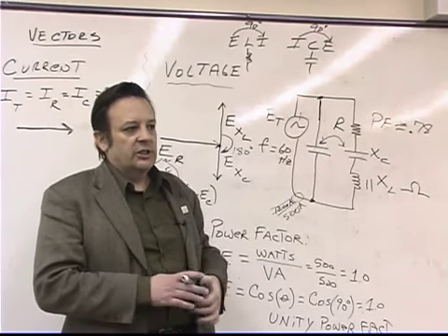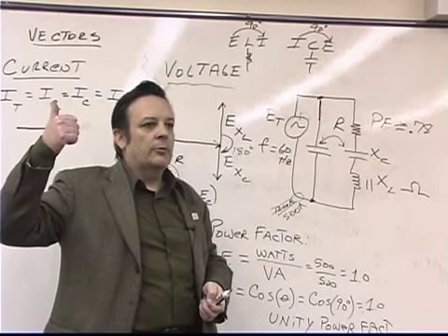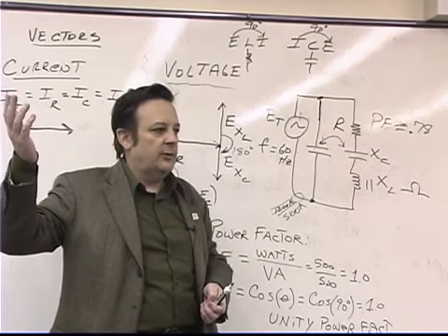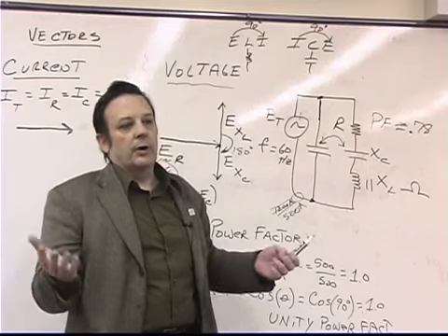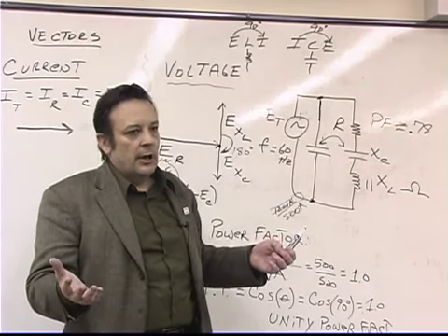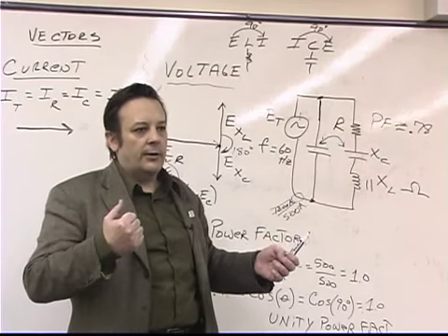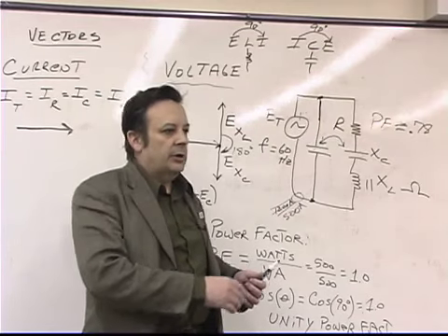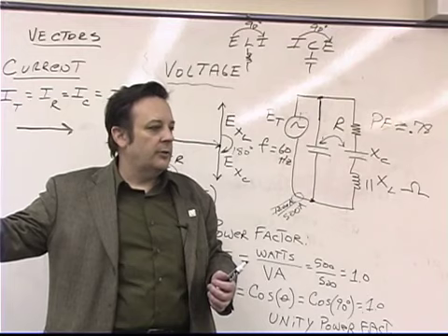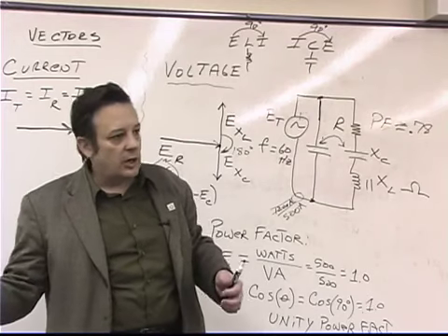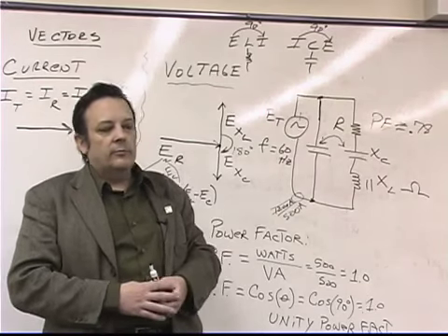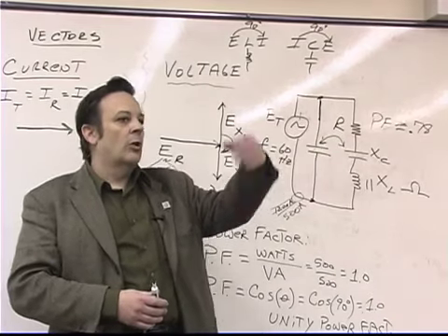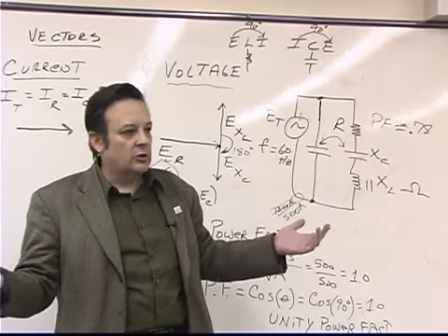Okay? So let's say that you have a compressor up on the roof that's part of your HVAC system, right? And this compressor is huge. Every time that compressor cycles on, the power factor is going to change. Every time somebody turns the lights on in the northeast end of the building, the power factor is going to change. Every time somebody turns on the motor for the roll-up doors, the power factor is going to change.